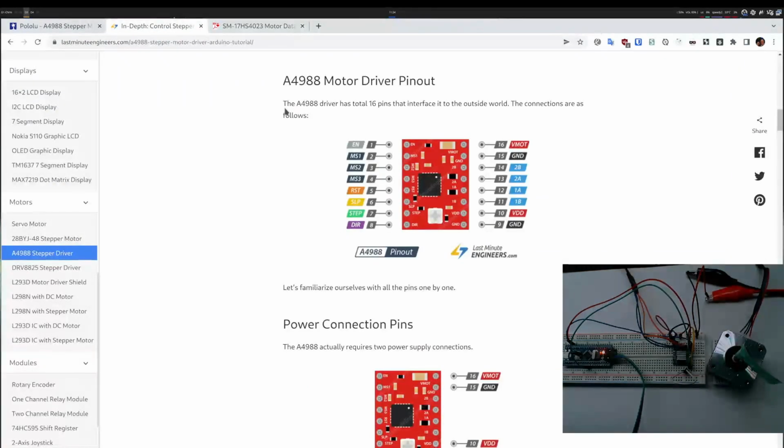And I will not be controlling the motor directly. I will control it using a motor driver, in this case an A4988. And this is reasonably complex, with many pins, but in practice what I need to control is just a step. So whenever I tell the driver move forward, it will move forward a single unit, and all the rest I actually pulled directly and did not control.